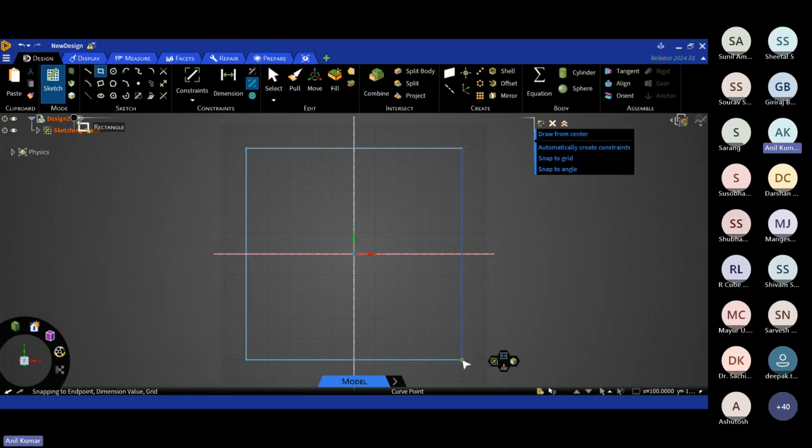So for example, we need not remove small features and everything, because it works meshless. Although we have some capabilities where we can control mesh size in the refine mode. We can define the local mesh size and global mesh size.